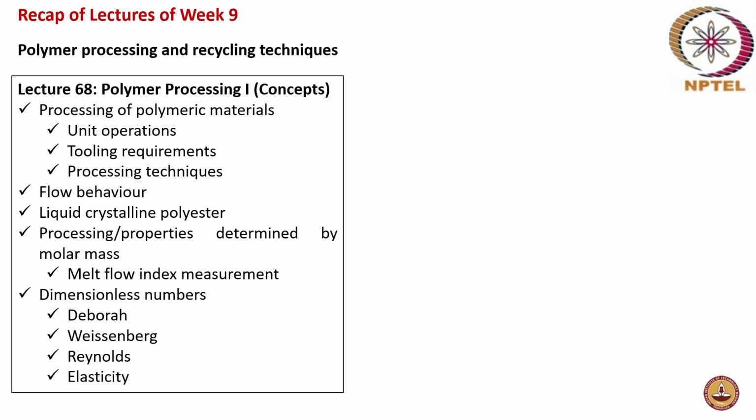And then there was a discussion on melt flow index measurement and the flow behavior. For example, in the case of polymers, you do not have Newtonian behavior. It will be non-Newtonian behavior. So how are the stress and shear rate related? And what are the dimensionless numbers in polymer processing operations? You have the Deborah number, Weissenberg number, Reynolds number, and elasticity number. So these were all discussed in